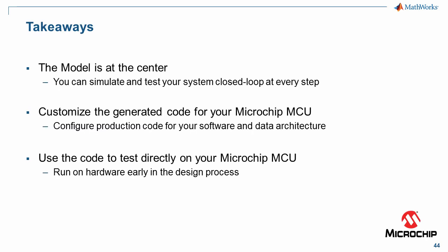We have reached the end of the webinar. As a summary, the 3 key takeaways. In our proposed workflow, the model is at the center. This means that the whole algorithm design is done in Simulink. Any changes during the development process have to be reflected in the model. Out of the model, we generate customized code for Microchip MCUs. The algorithms which we designed in Simulink are directly tested on a Microchip MCU with real hardware using rapid prototyping.